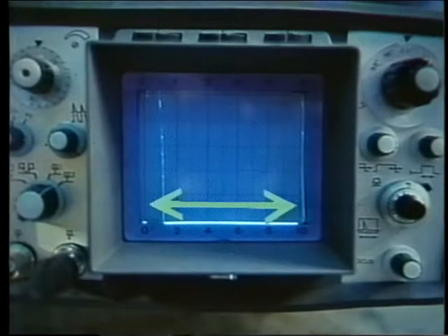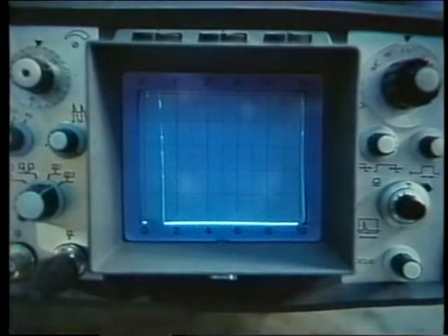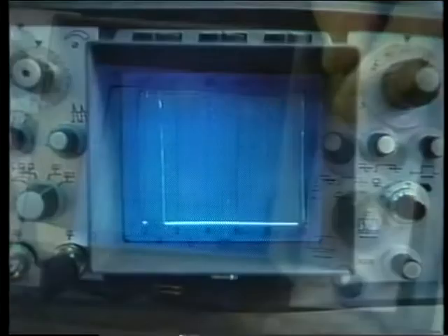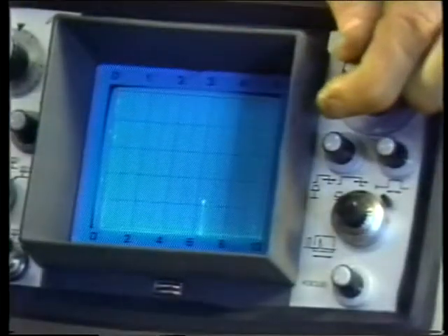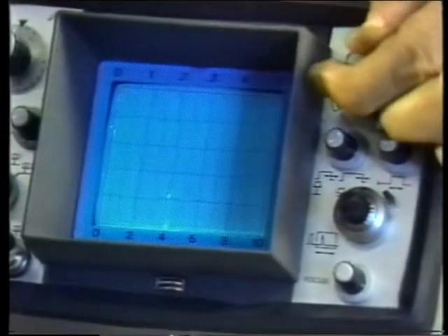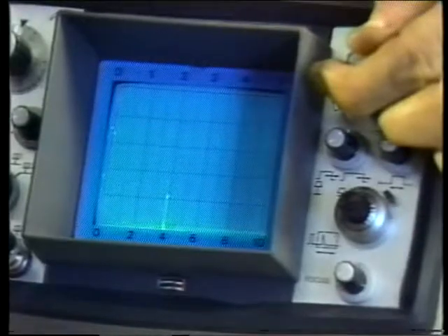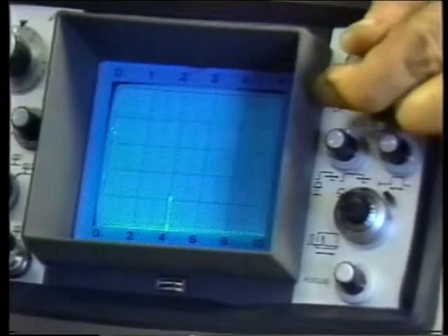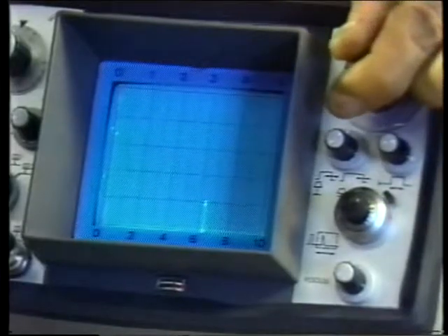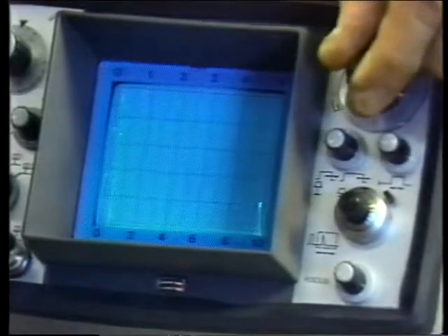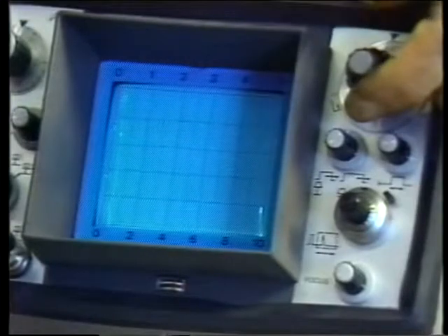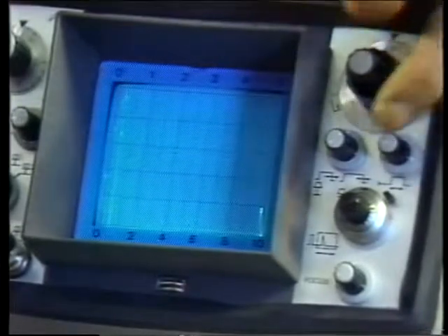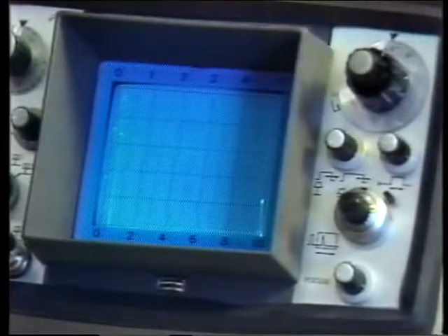We can adjust this distance so that our view of the part fills the whole screen. We can also match the spacing to the scale at the bottom. The test piece is 4 inches thick at this point. We can show 4 units between the initial pulse and the back reflection. Or for metric measurement, we can use a scale that shows the distance at about 10 centimeters. And now that the scope is calibrated, let's see what a defect looks like on the screen.